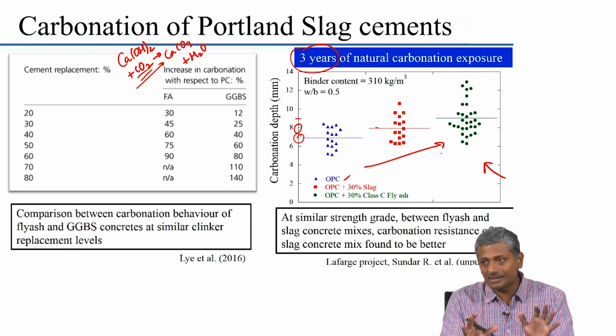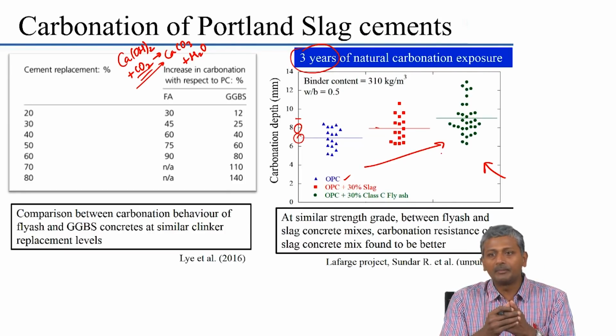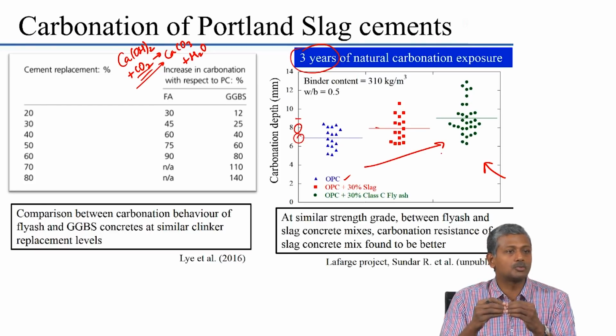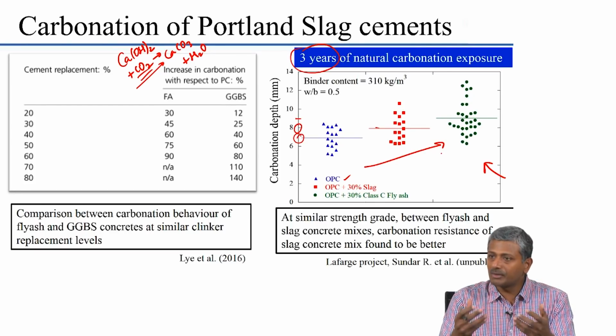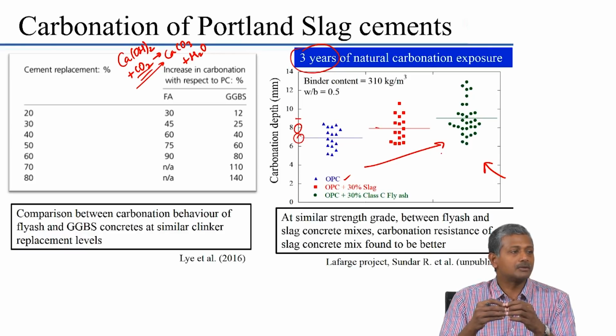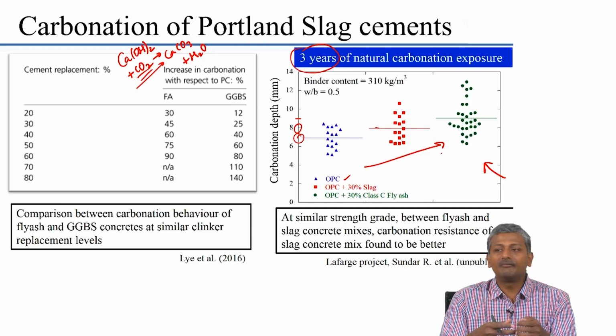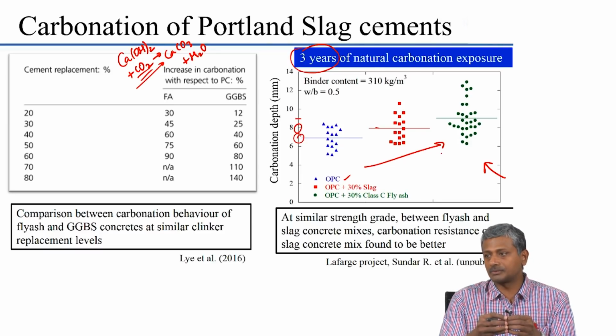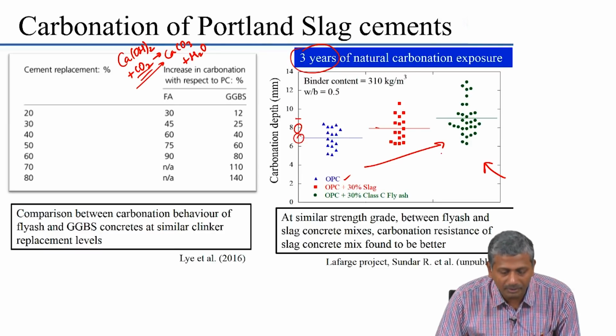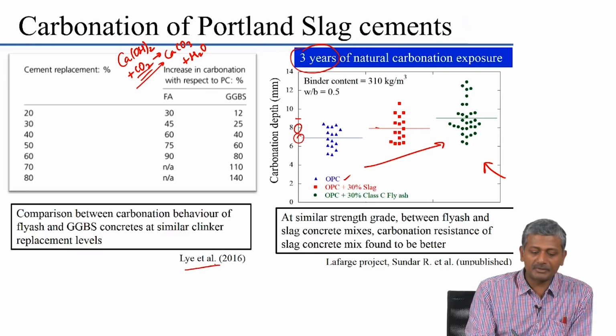But that does not necessarily mean that corrosion will actually happen, because the access to moisture could be quite limited. Okay. So, there is ongoing research which is trying to explore the humidity of concrete inside systems with different types of binders. Humidity level obviously determines the rate of propagation of corrosion. If you have less humidity, very highly resistive concrete, then obviously you are not going to get great risk of propagation of corrosion.